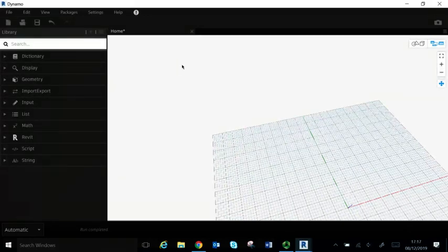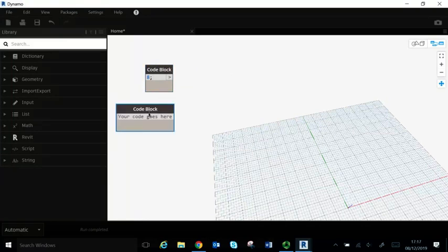So we can use these coordinates of a circle to place it by adding a radius, let's say 8, and angle. Angle going from 0 to 360 with, let's say, 10 degrees step.